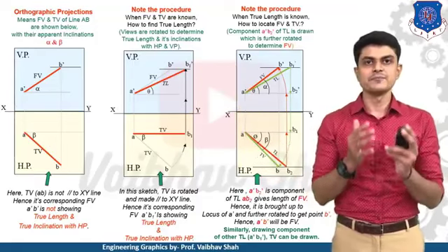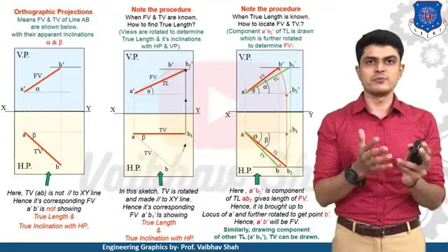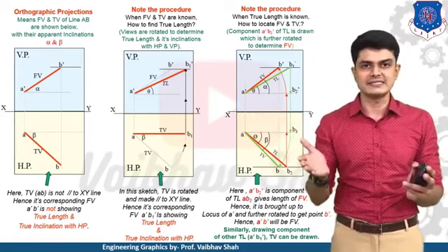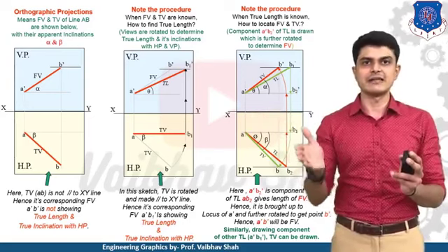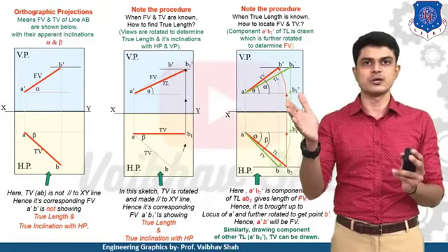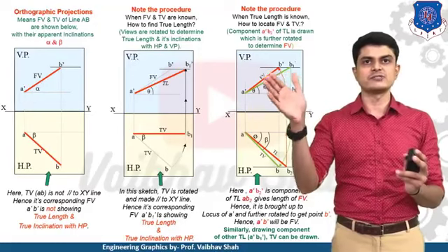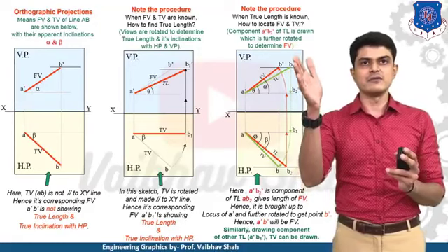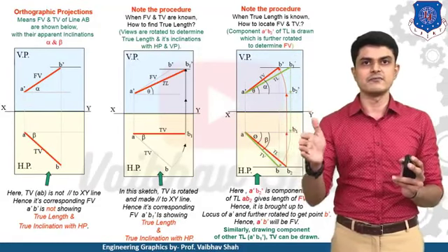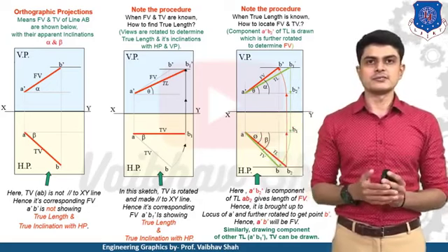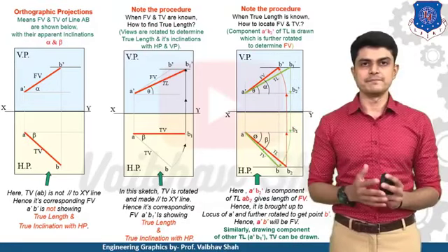Now let us suppose we don't have the front view and top view, but we have the two lines. So we'll first draw the two lines in both the cases. Then we'll draw the vertical line from the true length until we reach the dash locus. Then we'll draw the radius r. And if we have the true length of this case, we'll draw the true length at angle theta. We'll draw the vertical line until we reach the without dash line, and we'll draw the circular arc. Then we'll have this B.